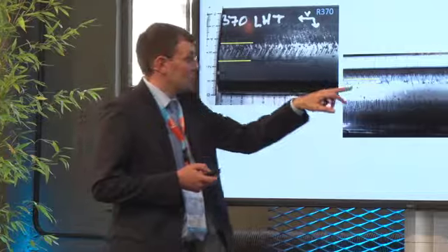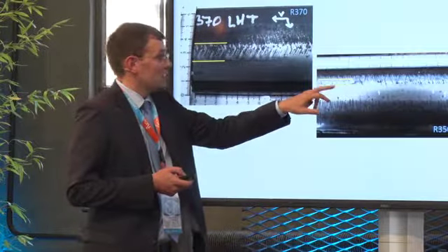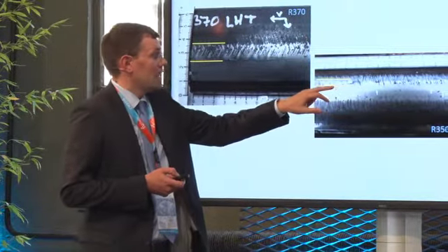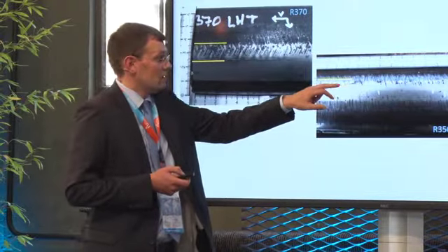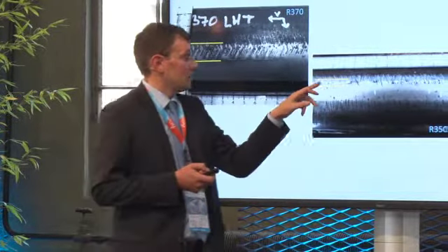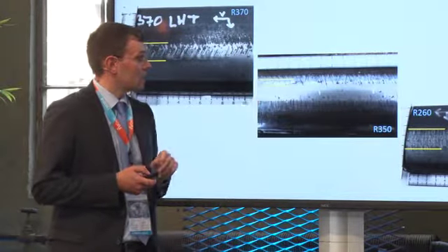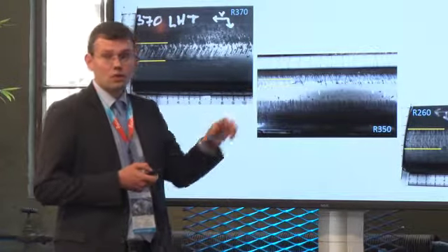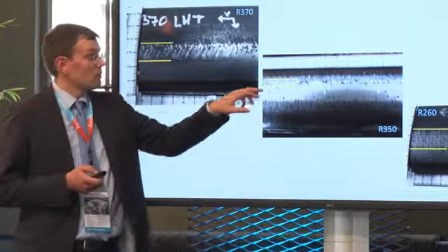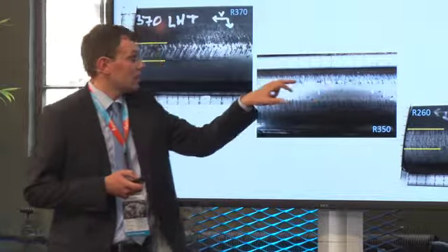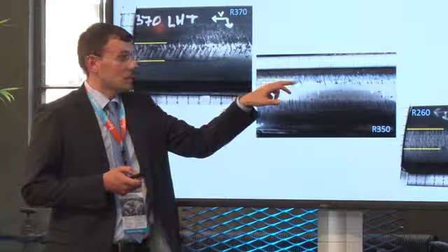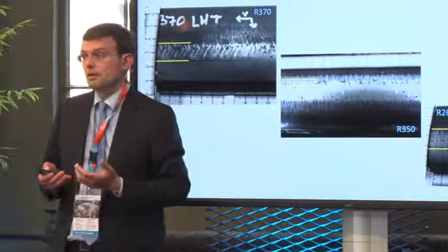When you look back to the history of these samples, in this case, for example, this is 350 and a high leg of a curve. Here, this seems to be related to an interaction of frictional work and roughness at the outside of the running band. So this is typically caused by spin. There's a lot of frictional work at this side of the contact, and in combination with roughness, this leads to phase transformation of the higher portions.